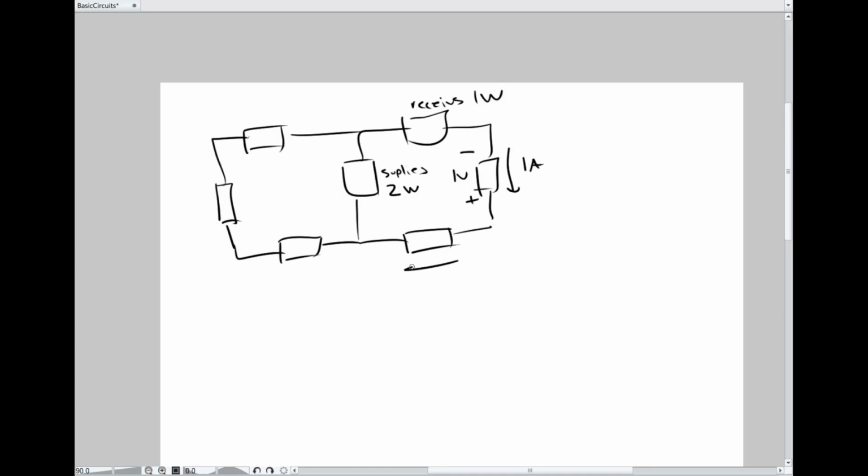And this thing still has 1 amp because they've got to follow Kirchhoff's current law still, and the voltage across it is, I don't know, 2 volts. And now I have to make sure that I don't really constrict myself by Kirchhoff's laws too much. Like, 1 amp goes here, if I define this current, now I define that current, which defines this voltage, because I define this voltage, which defines this power, which defines a current, and they can't contradict.